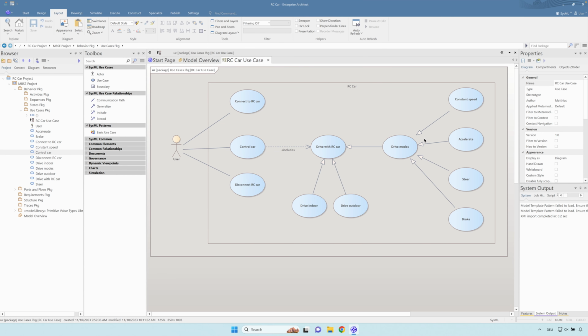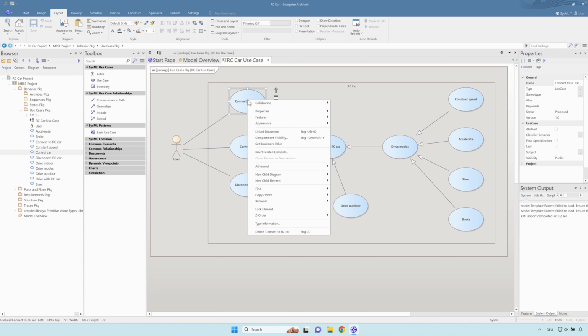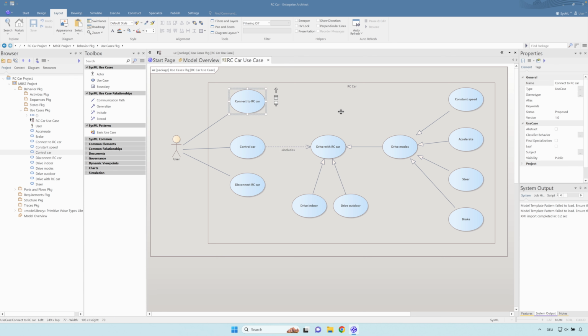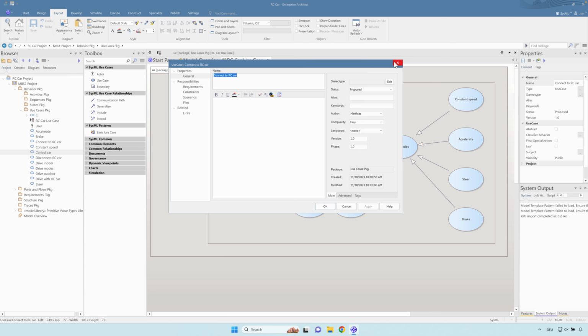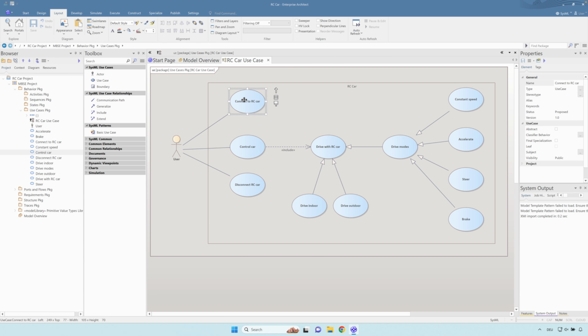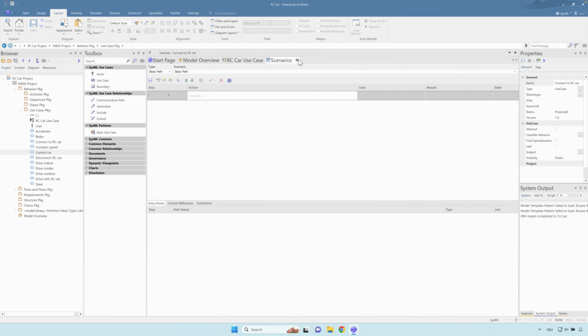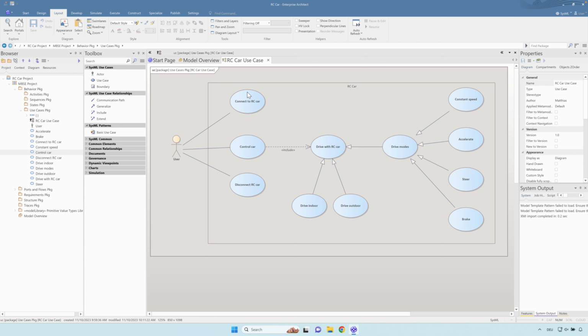With the use case diagram created in general, let's check some specific topics we also need for several other diagrams when we work with all the different artifacts. Right click on one of them and choose properties, and you get a new window. Sometimes you also get this just via double click on it. In that case not, we will check this soon.